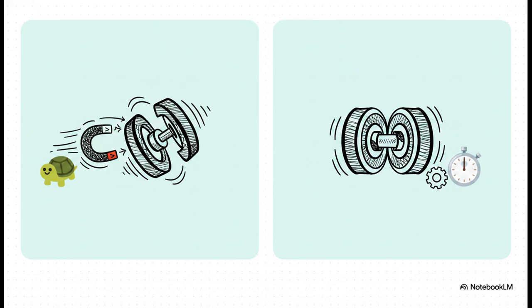Induction motors are asynchronous. They depend entirely on that relative speed, that slip, between the rotating magnetic flux and the static rotor conductor to generate the induced current. The rotor is always being dragged just a little bit behind the stator's field. Synchronous motors, on the other hand, play by different rules. At a steady state, the rotation of their shaft is perfectly, exactly synchronized with the frequency of the source current. There's no lagging, there's no dragging, just perfect harmony with the alternating current supplying it.